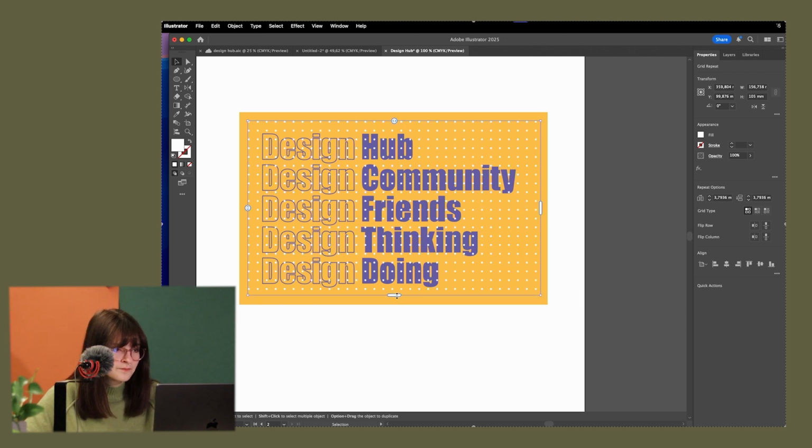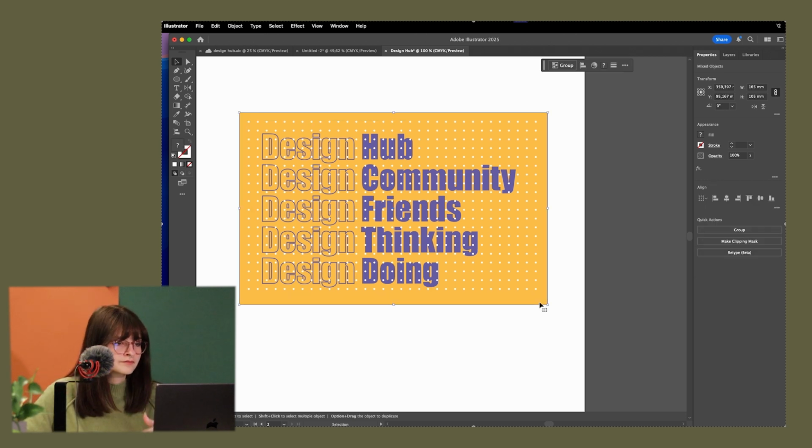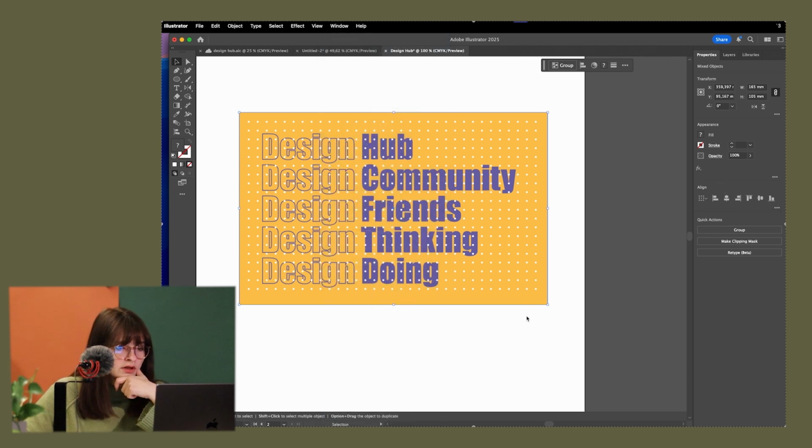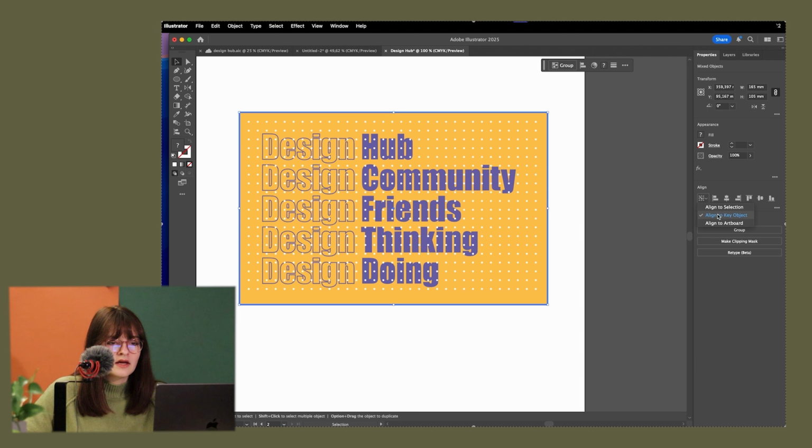You can also align it with the yellow thingy, which I'm going to do now. So I go shift and click on the yellow under background, whatever. And in the right panel, you have align. In case you can't find it, go to window and align in here. And I'm going to be aligning it to the yellow thing. So now I need to click on the yellow thing as well. You see, now it's encircled, which means that I'm aligning to key object. And I want to align it to middle, and it is nice, done.